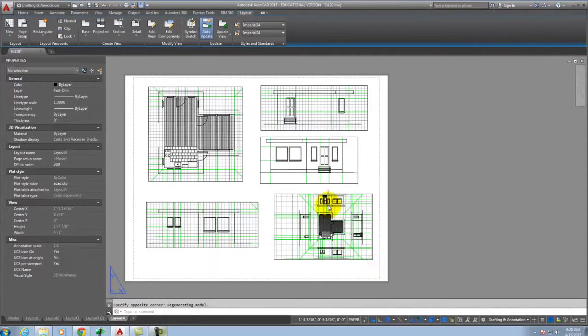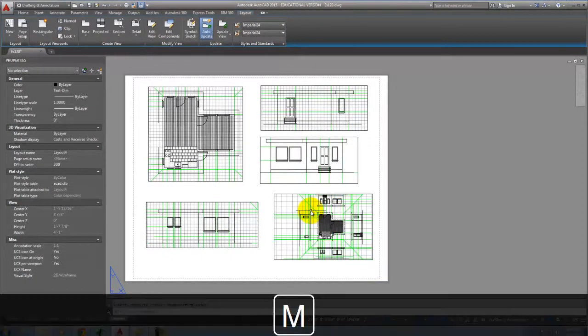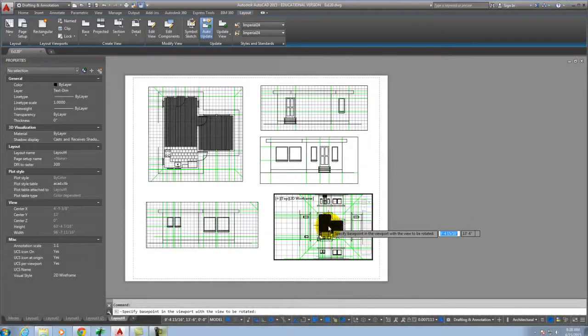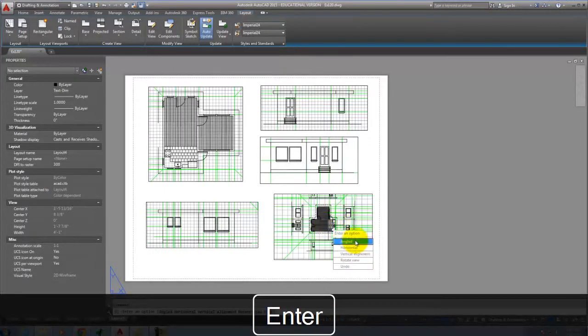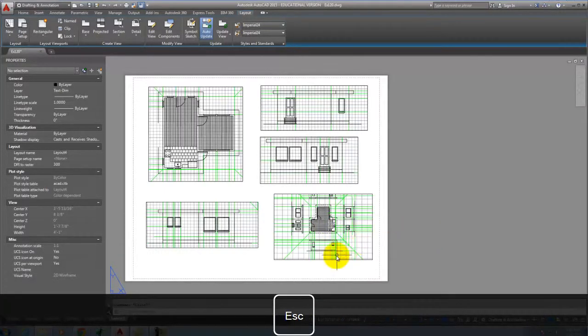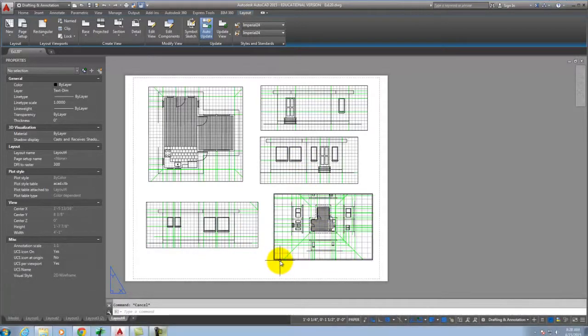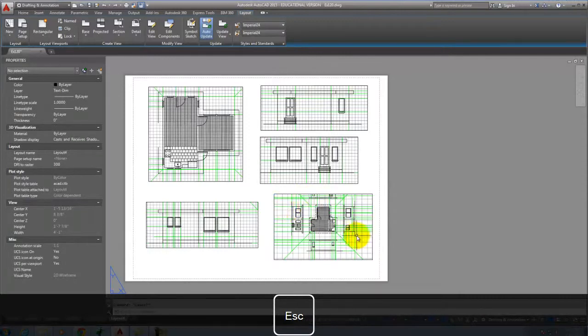One more right here. So once again, MV setup, align, rotate view. We'll click inside here. This one's going to be 90. You can see it rotates my view for me. And then we need to adjust my scale. Let me select it.